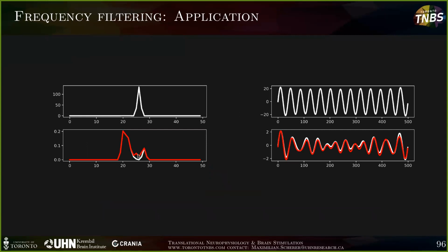This is because we can, for example, apply our filter as a band stop filter, which notches out a certain frequency. If we do that, we basically invalidate any information within this frequency area. It gets toned down by a significant amplitude, but doesn't get totally zeroed out. There's going to be some residual. And the more data you feed into it, the stronger the suppression factor usually. If you feed little data into it, like I did here on purpose, you're not going to even tone it down to 0. You're going to have some residual activity here.